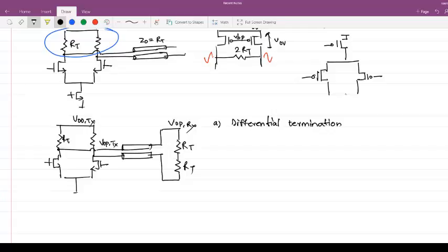And if you have a receiving amplifier, that should work at the common mode at the receiver side. So you are fixing the common mode on the receiver side by fixing the common mode on the transmitter side. If you want to work with a different common mode, either you use AC coupling in the path, or some kind of level shifting on the receiver side. Both are very much utilized.